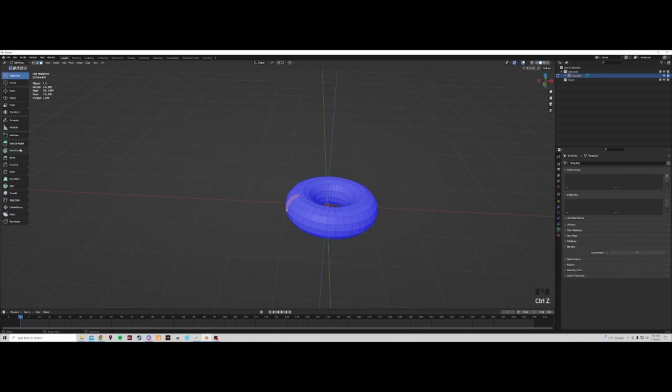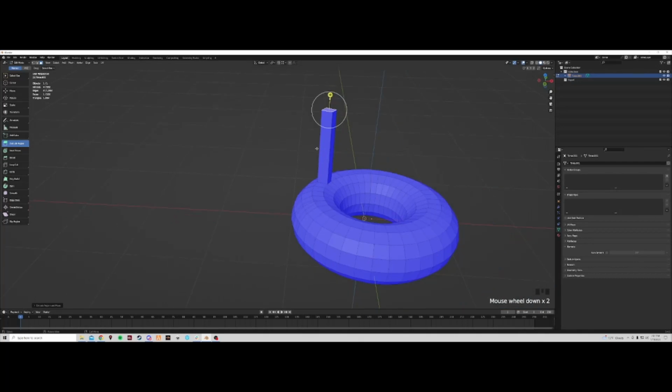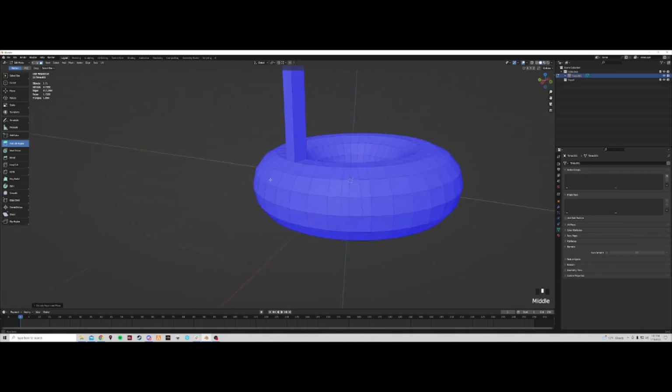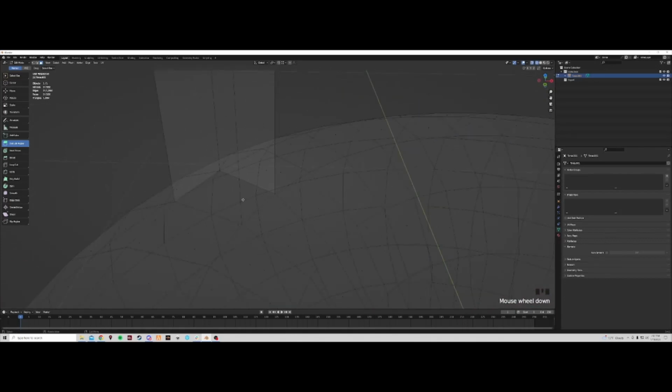Speaking of extrude, did we skip to that one? Okay, so extrude. If I take a face, and I click on extrude, I can grab this little plus line right here and drag it out. It will create faces as it lifts up the face I just selected. But where I originally selected it, there is no longer a face here. It is empty area.